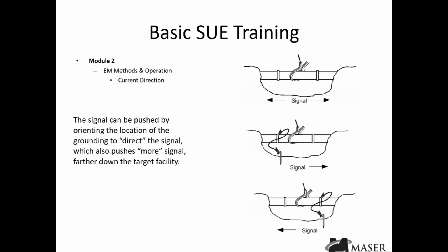Now, if you had moved past the clamp and were 100 feet to the left of this graphic and you kept facing towards the left and moving away, then you would notice that the current direction is moving in the same direction that you are, moving away from the clamp. If you turned around 180 degrees and started heading back, your current direction would indicate that that signal is heading straight into you. You move down to the next graphic.